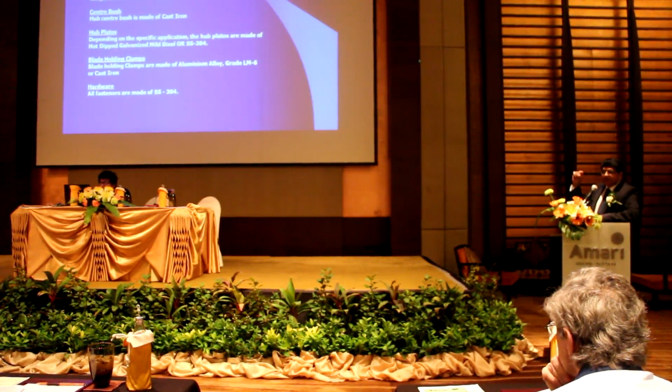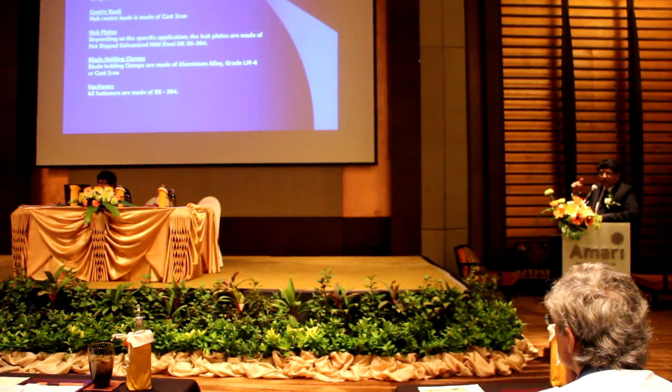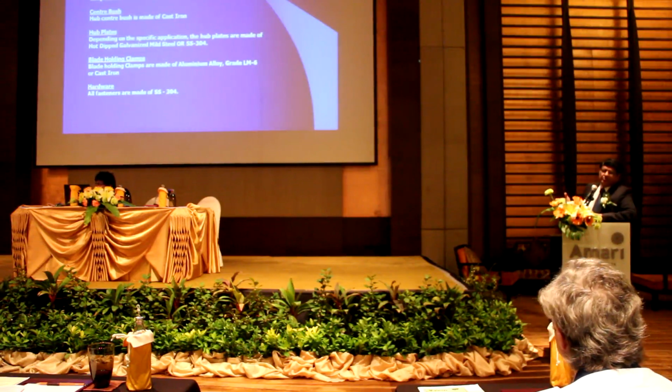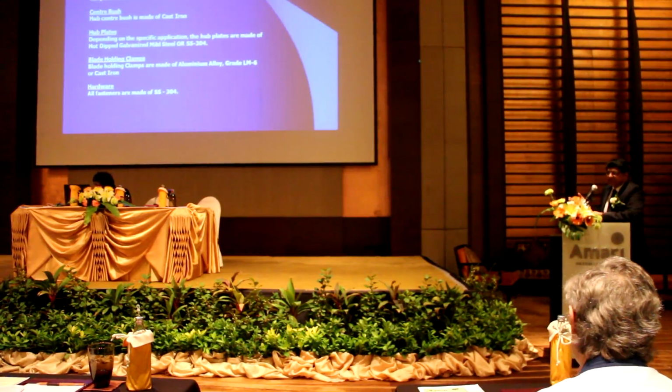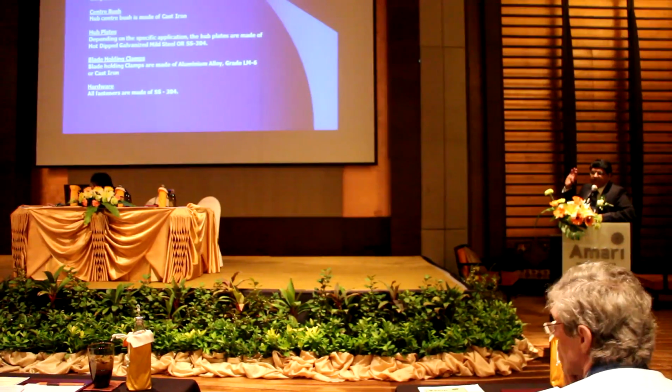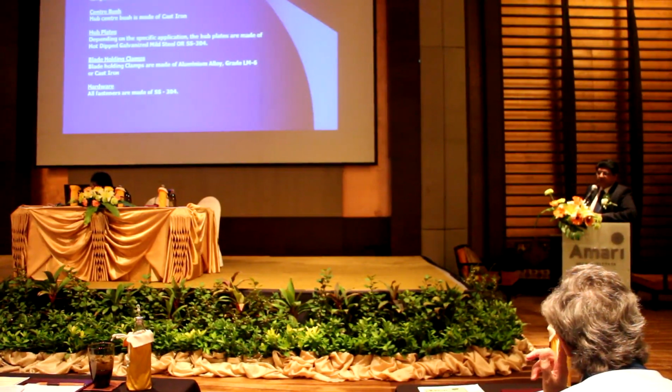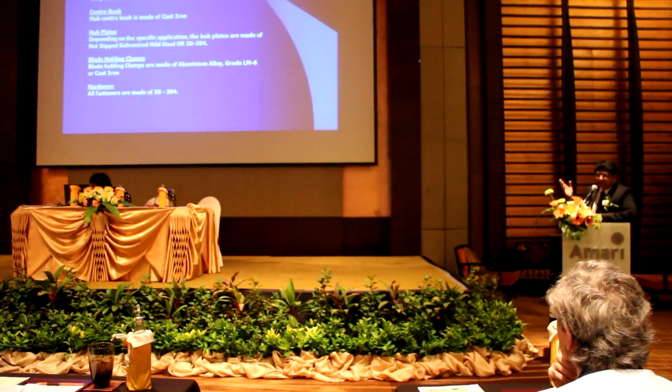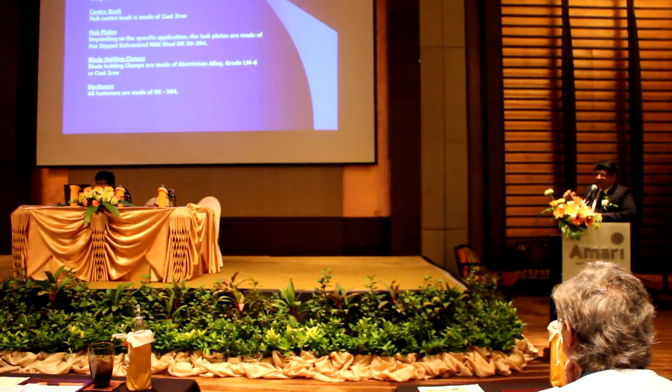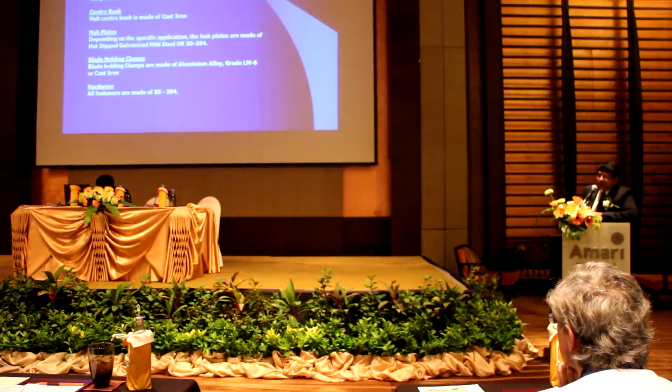We are not talking of the effluent that is going in the tubes. That may be at 230 or 240 degrees, but finally the heat that is seen by the blades is of the order of 120 to 150 degrees Celsius, maximum, even if one fan is off. We can specifically give, and recently we have done some work to go up to about 200 degrees Celsius continuous exposure. The center bush, which gets onto the fan shaft, is made of cast iron.